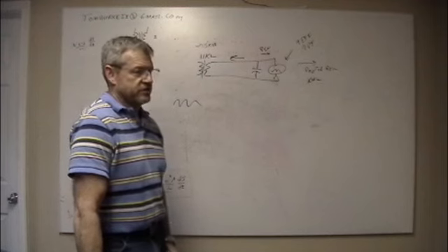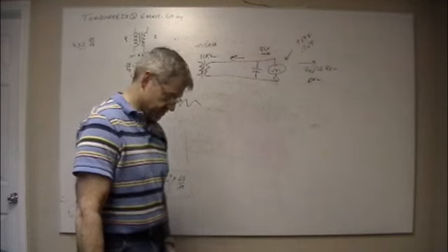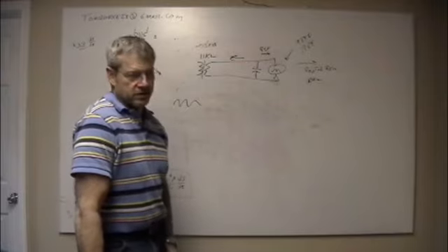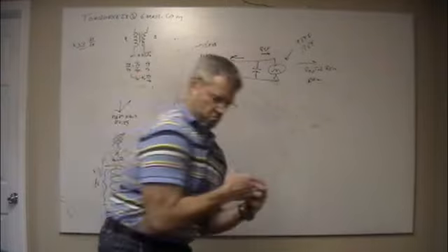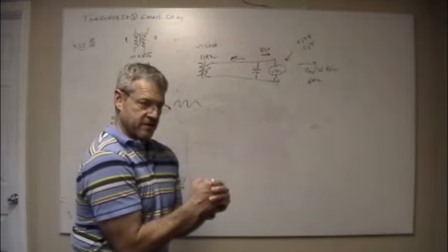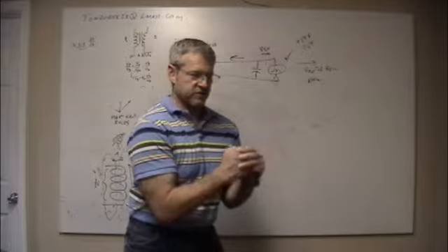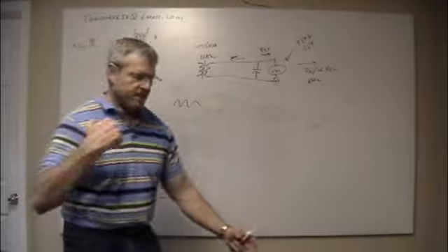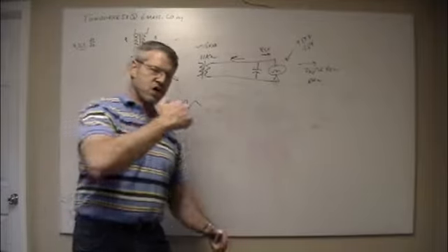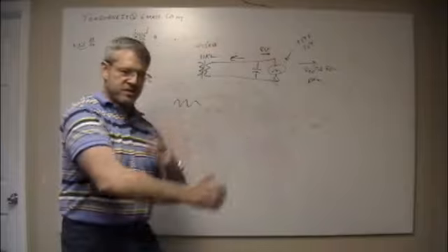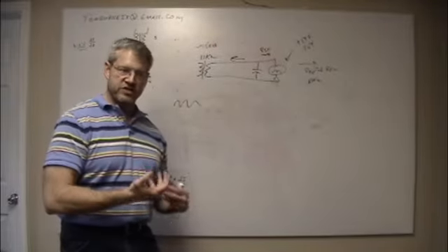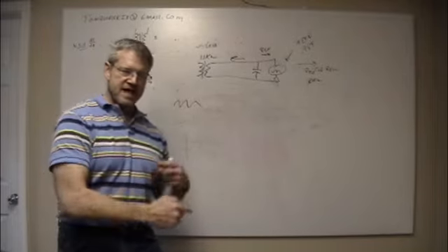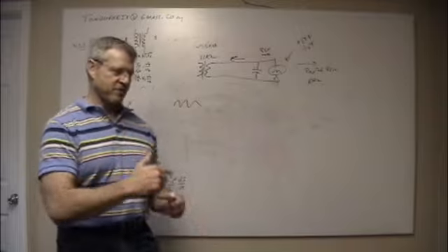And there's actually inrush currents and start currents, because when you first start it up, that thing's sucking a lot. What's the word, not crowbarred, it's locked rotor current. If you lock the rotor in place, that's the current it's going to draw, because once that thing gets moving in there, it creates a reverse EMF, electromotive force, and once you get up to speed and things are running, it doesn't take as much. It actually generates a little bit of reverse power. Any motor is a generator. Yeah. It's kind of funky the way it works.